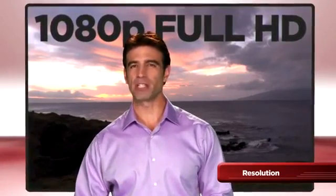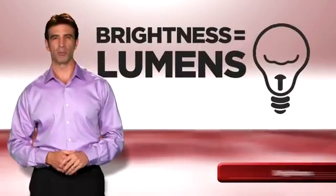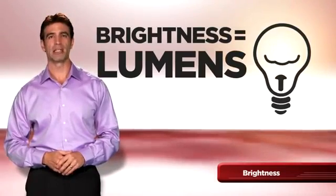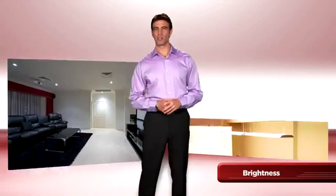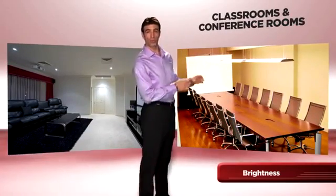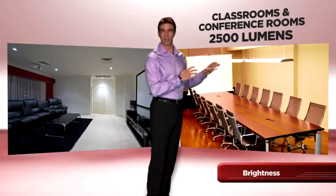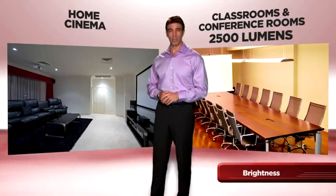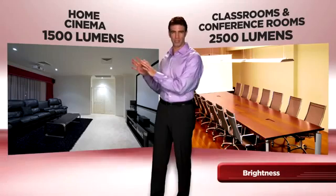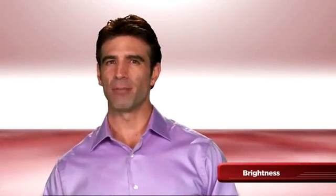After you have found the ideal resolution and decided on widescreen or standard screen size, it's time to choose the right brightness level, which is measured in lumens. Now, the amount of brightness you actually need is determined by the room you project in. For projector use in classrooms and conference rooms, or rooms with outside windows, choose a projector with a minimum of 2500 lumens. For home cinema projectors, appropriate for theaters where ambient light is kept to a minimum, you'll require around 1500 lumens.